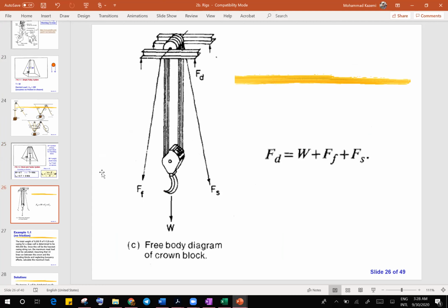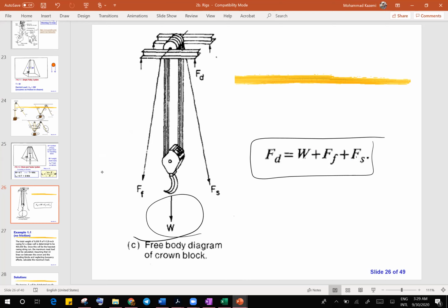But overall, the main equation that you see also in your equation sheet is this equation. This is the derrick force. The derrick force is calculated based on the weight of whatever drill string is here, and the fast line force and the deadline force. So these three forces make the whole force on the derrick. This is again the crown block, and this is called the traveling block.